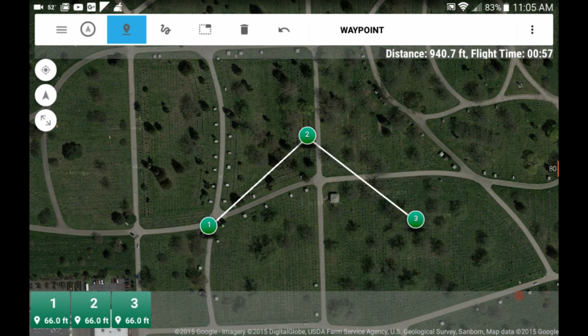Okay, and we're going to talk about this mission as it is. Now, when you play with Tower, there's a couple different ways to go about it. You can set up a fully autonomous flight, or you could set up a flight where it would be required for you to control the landing and the takeoff. Okay, this mission you see here on the screen is just a simple fly from waypoint 1 to 2 to 3 to 4, and there's no takeoff and there's no landing involved.